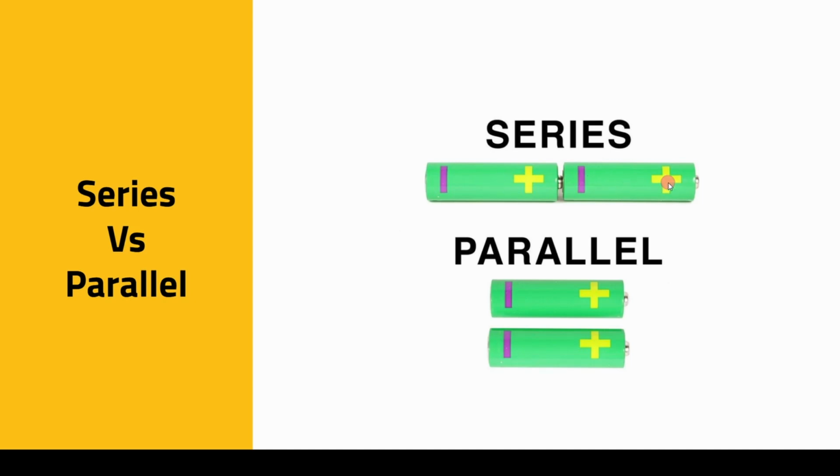So, the total voltage will now be 3 volts, but the current capacity is whatever is the capacity of any one of these batteries, right. Ideally, they would both be similar. So, if these batteries are able to supply 100 milliamps of current, then that is the maximum current that you will be able to draw through this series combination at a voltage of 3 volts.